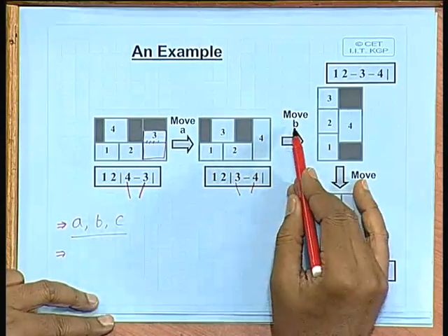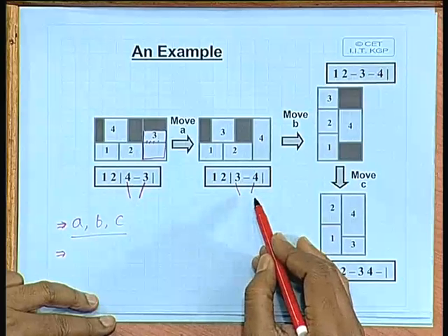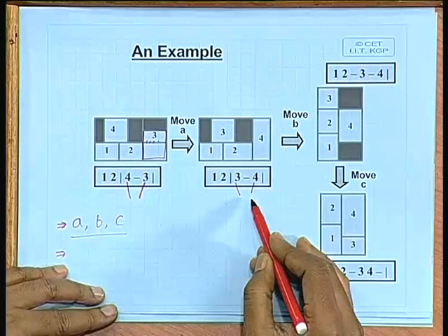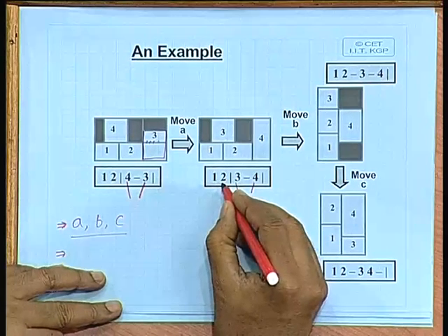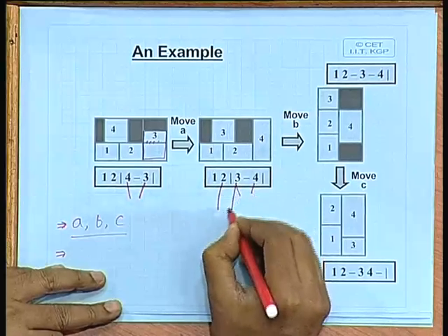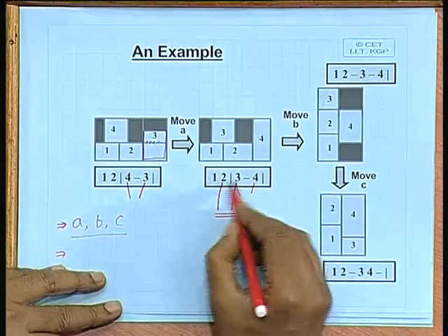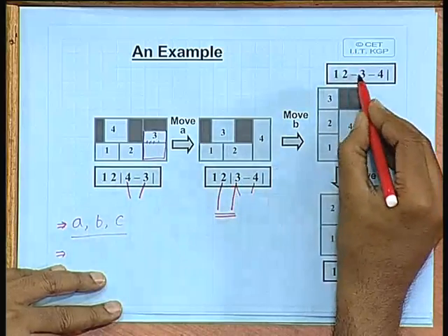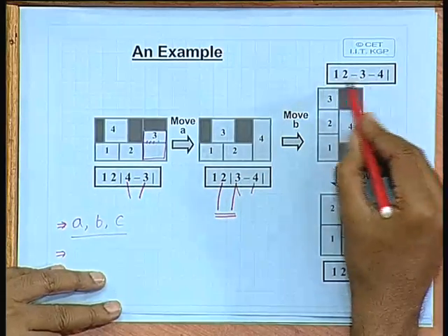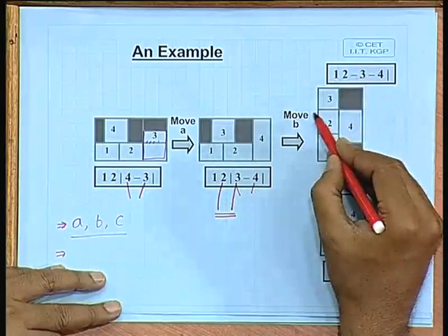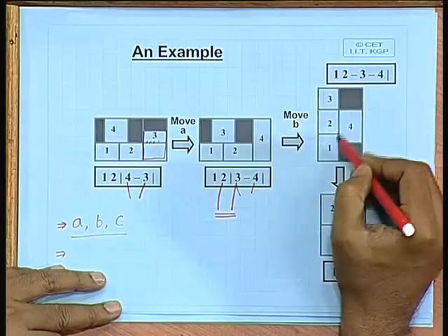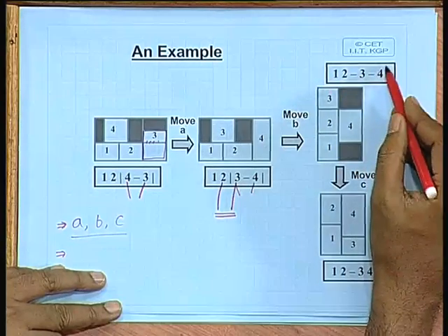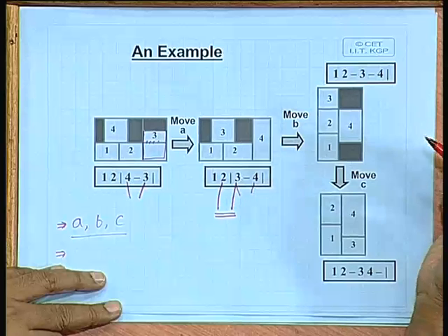From here, if you want to make move B, you have to define a chain again. Here the way the chain is defined is that, say you define the chain between 2 and 3, these 2 operands. In fact, incidentally within these 2 operands there is a single operator, you change it to horizontal. So, now this says that 1, 2 and 3 all will be separated by horizontal slices, and this entire thing and 4 will be separated by a vertical slice, something like this.